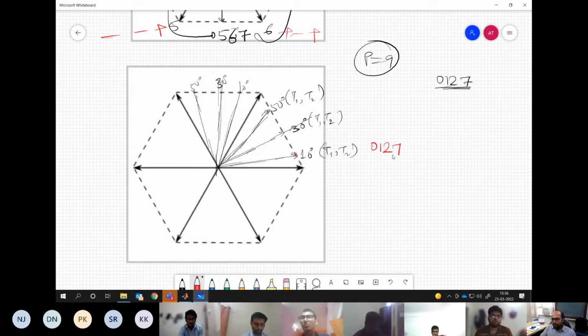The next one, same rule applies here also. You have to continue with the 0 vector which is ending this sample, which means 7. Then the next active vector, or closest active vector, is 2. Then 1, then 0. Now again you have to continue with 0, 0, 1, 2, 7. So 3 samples will have this kind of vector sequence. You cannot have 0, 1 to 7 in all 3 places because you will encounter 3 switching when you jump from 7 to 0. So you must continue this.